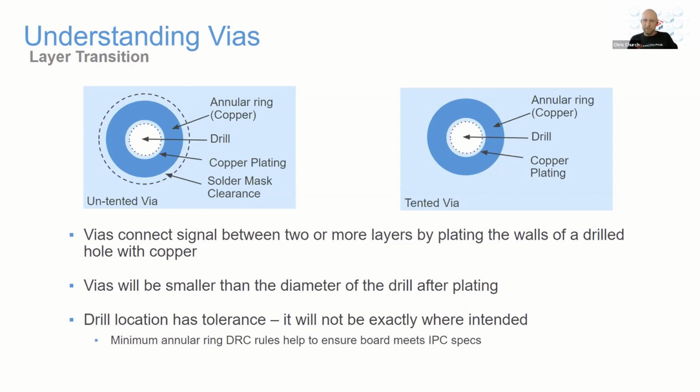We get questions a lot because when we talk about the tolerances on a via and the drill hole size, they'll typically be expressed like it can be plus 0.5% or negative 100%. And people go, well, how in the world could it, you have no hole there? Well, the answer is the plating process could, depending on the size of that drill, actually fill the entire hole with copper. So that's why they'll express it that way.